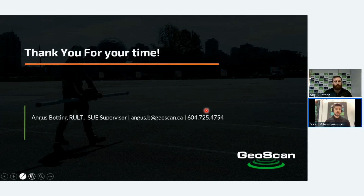Okay, and Kate asks, does GeoScan offer utilities digitization from paper as-built drawings? Yes, so we offer a service where you could send us your entire utility records for a terminal or a private site, and we could take all your utility records, conduct our field investigation at the same time, and put them together. Or alternatively, we can do a quality level D in-house desktop study, bring in your utility information, then highlight areas of conflicts or areas that don't fit based on the records.